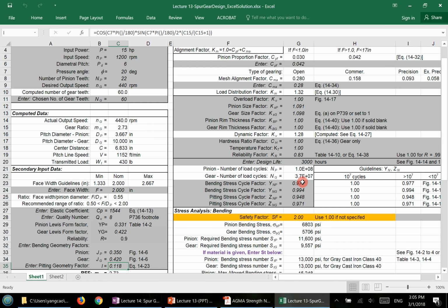Okay? Because the system you're designing is basically a completely coupled system. Okay? And I think I'll talk about this in the next lecture when I roughly finish the shaft parts. Okay, yeah. So very possibly, and actually not just possibly, it is a must. You will design the shaft first, then you will go back to look at the gear again.